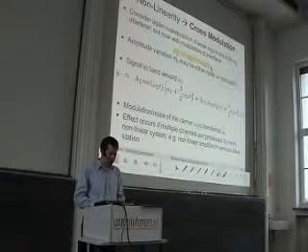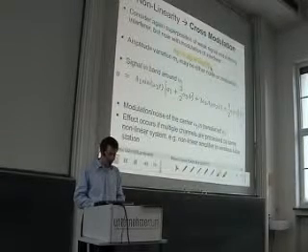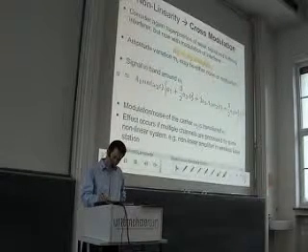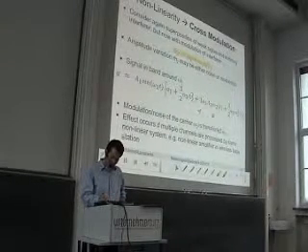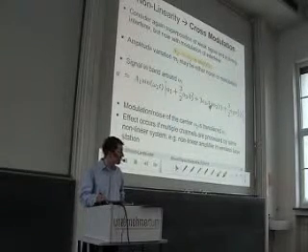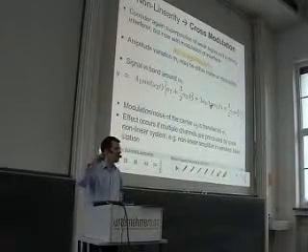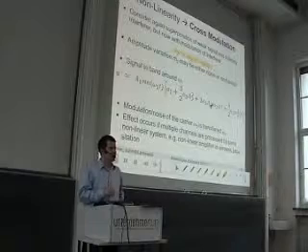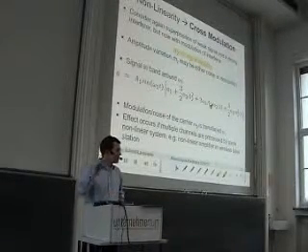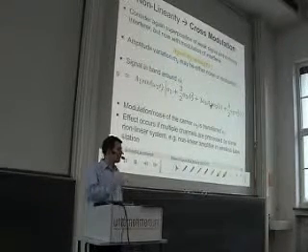The calculation is the same, except that the equations become a little bit more complicated. But if you look at this term, you see again we have this desensitization term that now also contains the modulation. This means if we have a varying signal on a frequency omega 2, this modulation is also seen at the first frequency.